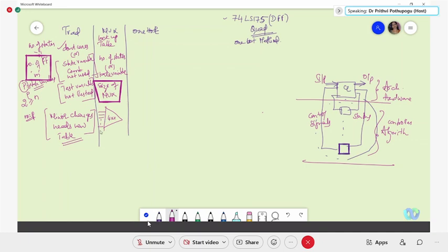Each input of the mux corresponds to a state. So these selection lines, I can take as the number of state variables, that means P. I'm generalizing that now. So P. How many state variables you have is decided by the number of states, and that number of states will be the inputs of your mux, and the state variables will be your selection lines.